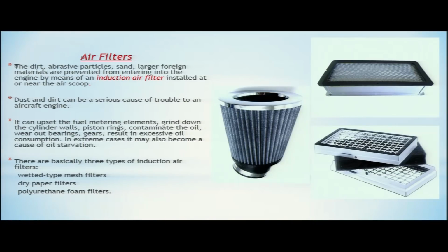What can be the problems? Because of dust and dirt, it can upset the fuel metering elements, grind down the cylinder walls and piston rings, contaminate the oil, wear out bearings and gears, and result in excessive oil consumption.